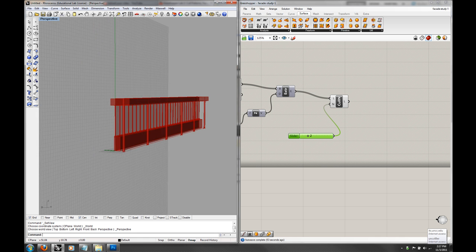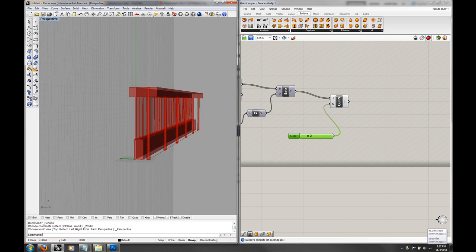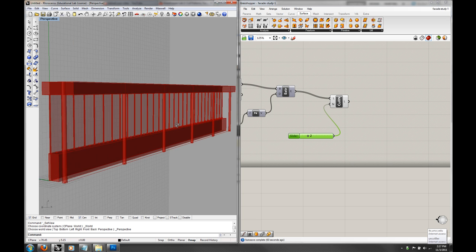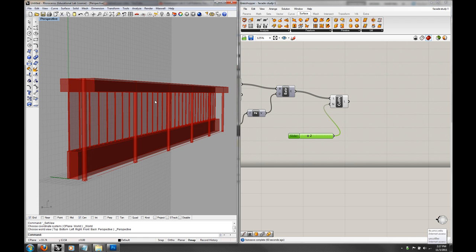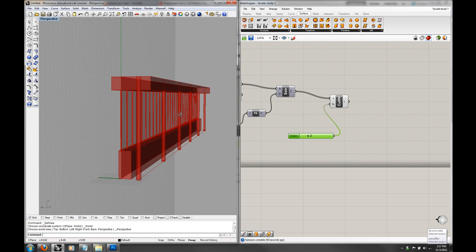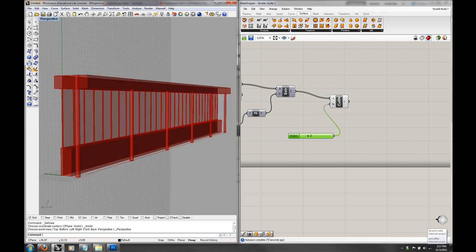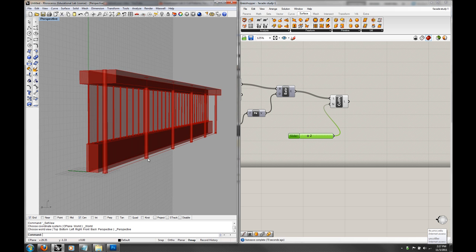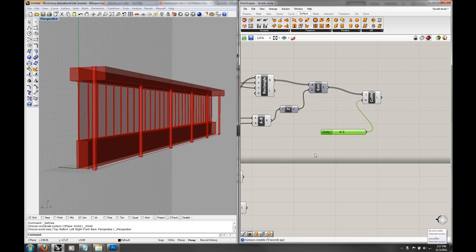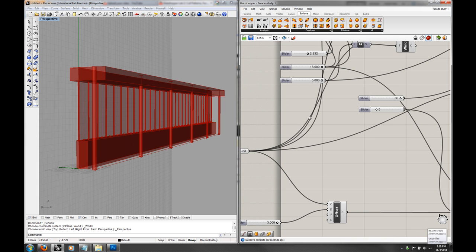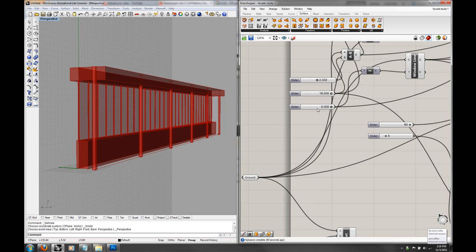So there's that. There's one design there. We could also go through and make a copy of this line. We could move it, and then we could extend a cross section, and we could further subdivide this. We could divide this into 2 windows and have one window that has this pattern, and then another where this is culled even further, to create kind of a clerestory window. So lots of things. So it's kind of a basic demo of how to do this facade assignment.